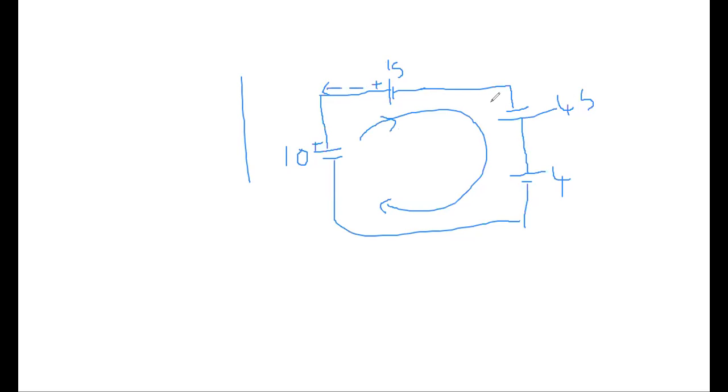Okay, right. Now, this is 45. Tell me now, is 45 plus or minus? Plus 45. Plus, because if you see here, you have to compare at this condition. This is a positive terminal and current starts in this direction, and loop current is flowing through the entire element. So here you are supposed to compare the direction of the loop current and the direction of the conventional current of 45. Both are in the same direction. Therefore, it is plus 45.